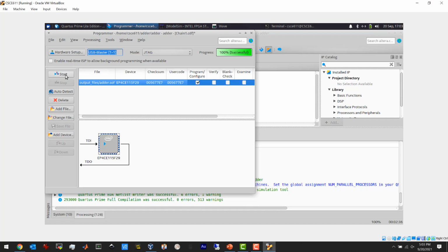And also make sure that there's a switch on there somewhere. Oh, this switch. There's a switch that you want to always be in run mode. I think the program mode is for programming that flash I was telling you about. You want to have it in run mode. And likewise, I didn't use any of the buttons, but you're free to. Oh, and there's also memories. So basically, whatever you put in the top level, you have your top level design. Whatever you put in the module line determines which of the components you want to communicate with on the board from the FPGA. All right? Okay.